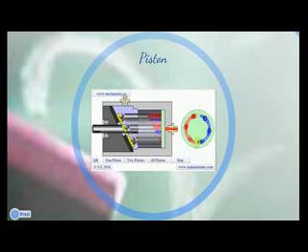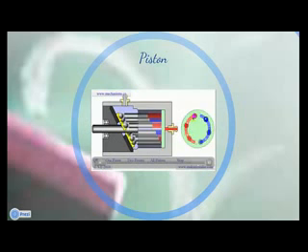When the colors of the discs are lighter, the piston is closer to the port plate, as shown in this section of the animation. And if the colors of the discs are darker, the piston is away from the port plate, as shown in this section of the animation. This is how we can tell whether the port plate shown represents a pump or a motor. Since the red discs on the red crescent change from a deep red to a lighter red, this signifies a pump. If it were a motor, the opposite would be true.